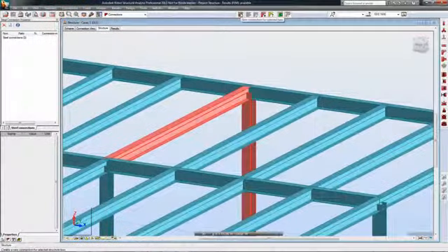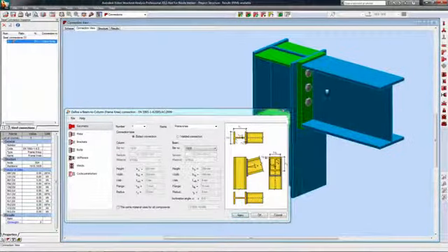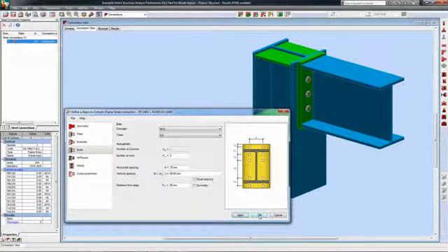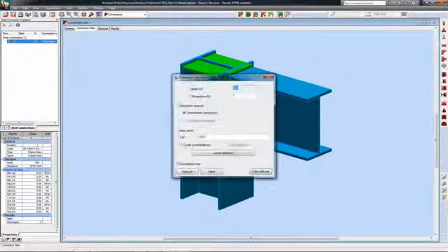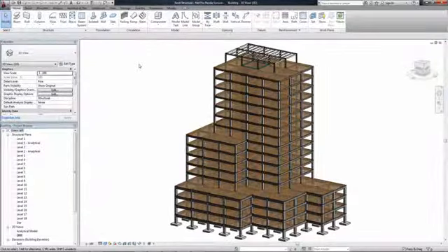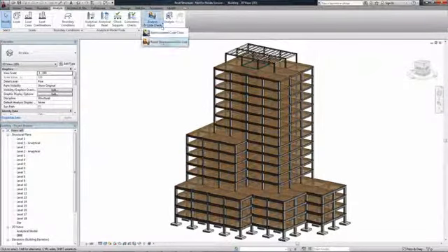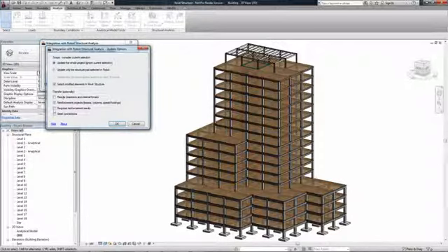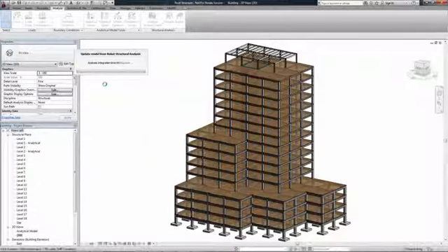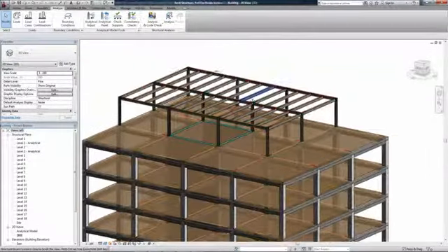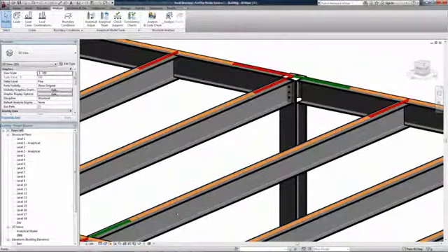Once design changes and the analysis have been completed, the information needs to be brought back into Revit Structure to allow the designer to review the design changes from the analysis and code checking phase and update the physical model accordingly. In Revit Structure, via the bidirectional link with Robot Structural Analysis Professional, a designer can review, accept, or even reject the engineer's proposals represented in the analytical model, or even suggest another solution, while keeping in mind the engineer's suggestions. All changes to cross-sections and materials can be viewed in the physical model as well.